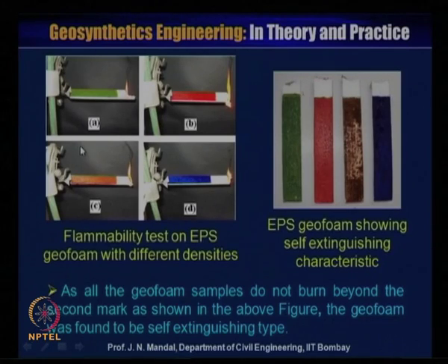You can see here the flammability test on expanded polystyrene geofoam material of different densities: 15, 20, 22 and 30. This is EPS geofoam showing self-extinguishing characteristic. You can see here is a burning, and after that you can see the end of the burning here.